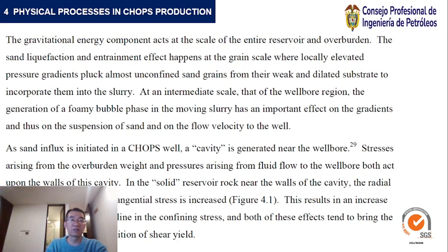The sand liquefaction and entrainment effect happens at the grain scale, where a locally elevated pressure gradient plucks almost unconfined sand grains from their weak and dilated substrate to incorporate them into a slurry at an intermediate scale, that of the wellbore region.